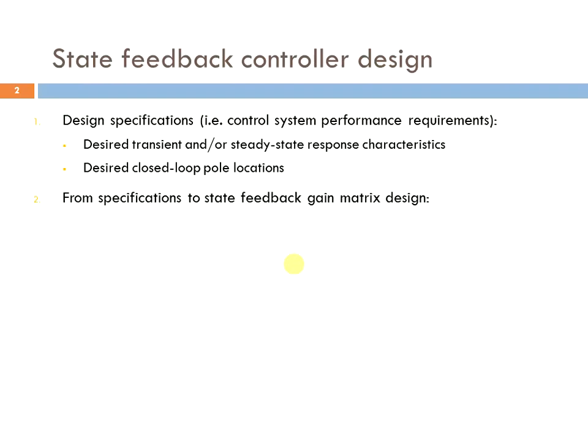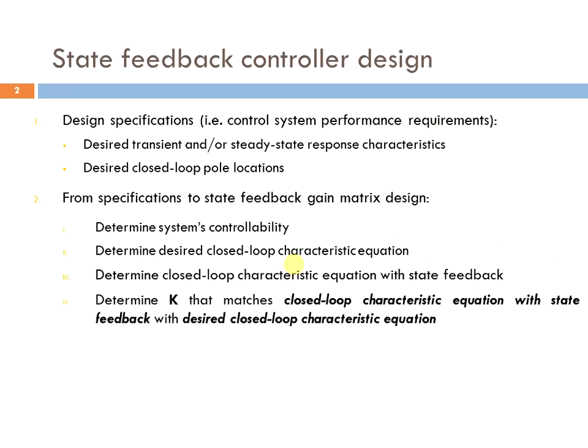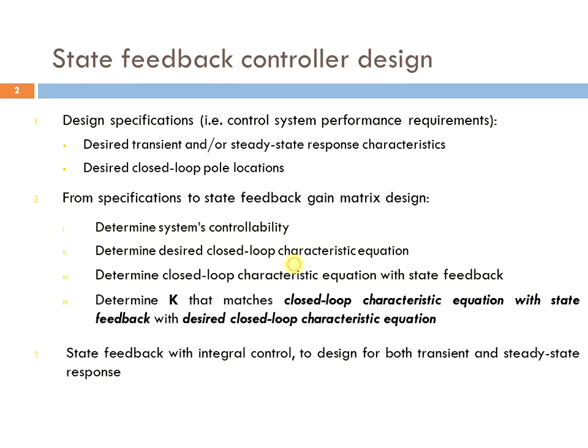We also looked at how, based on the design specifications, to go on to design our state feedback control matrix, starting from determining the system's complete controllability, right on to calculating the elements of the state feedback matrix. The other thing that we looked at was how to design for both transient and steady state response.